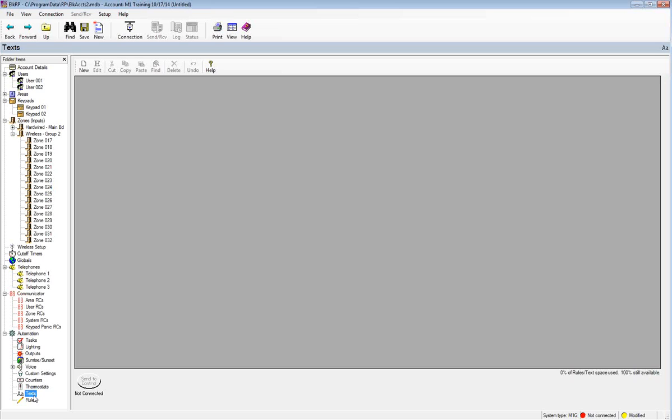You can also create custom ASCII strings under text and have that sent out the M1 either through serial port 0, the onboard serial port, which can go to third-party equipment such as Control4 or Crestron or so forth, or through the XEP module out onto the local area network, or through our serial port expander, the M1XSP.